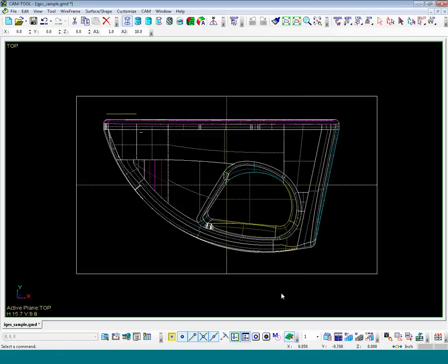For this demonstration, we're going to use layers 1, 10, and 15. Layer 1 for the geometry we want to cut, layer 10 for our stock model surfaces, and layer 15 for our calculation boundary. Now, if we want to make geometry directly on a layer, we have to use this window right here. This is called your active layer. Whatever number you have in here, that's the layer number new geometry will be created on. So we've set it to layer 10, and we're going to create the surfaces we need for our stock model.